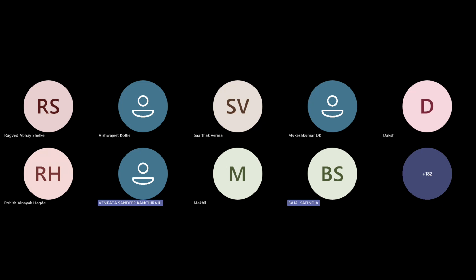Sir, in vehicle dataset generation, should we select automatic in gearbox as well, or use a gearbox, as we are using CVT? For the CVT, we have a continuous variable transmission option in CarMaker itself. Please check that, and you can configure it with the help of that.